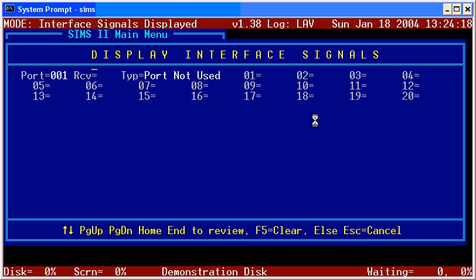We have all of the manuals for all of the receivers, but in today's market, with the way receivers open up portals to panels out in the field, they really can't guarantee what we're going to get in anymore. In the case of a SIA, that data comes directly through from the panel through a port right into the computer, and the receiver manufacturers have very little control over that now. That's a whole other subject about whether they should have relinquished that or not, but just know that there are many, many times we're going to have to ask for display interface signals if we're dealing with a signal type problem.